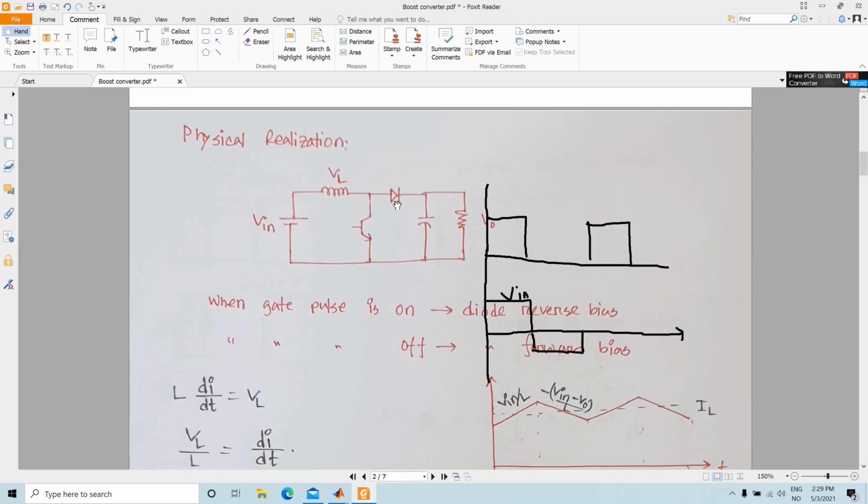It is also valid for the diode. During the time when the diode is on, there is a constant voltage drop across the diode, which causes a power dissipation across the diode. For the switch or the transistor, there are basically two kinds of losses.